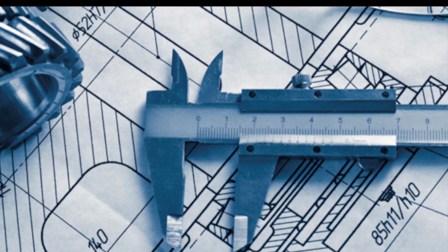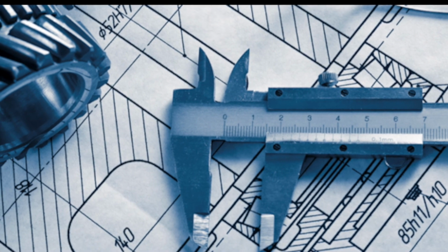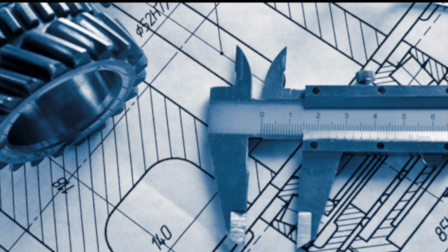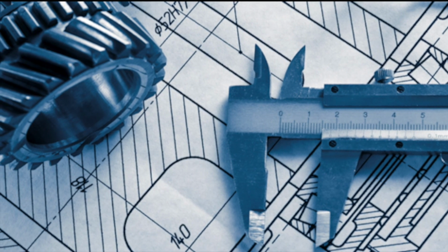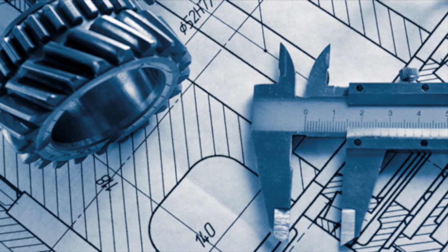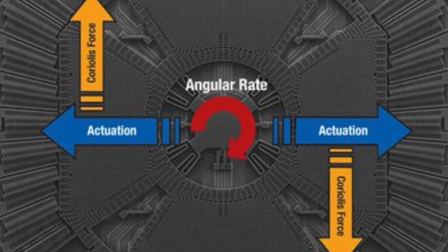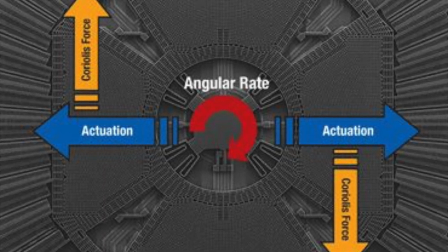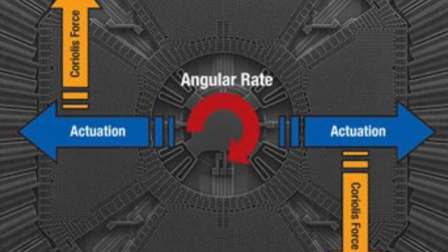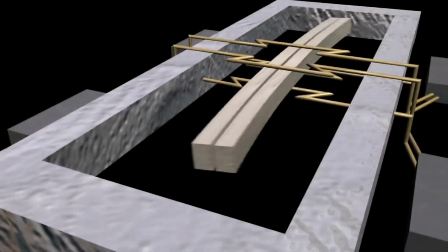The pendulum doesn't just have purely scientific value either. It has very important applications in engineering. An object in oscillatory motion being used to measure the rate of rotation of its reference frame through analysis of the Coriolis effect is the basis for the instrument which marks the biggest leap in technological advancement since fire. The MEMS gyroscope. That's right, as we all know from MTE 202, MEMS gyroscopes force a mass to vibrate in one plane and allow the rotation of the device to force the mass to move in another plane. And the mass's position is measured on this axis in order to determine the rotation.